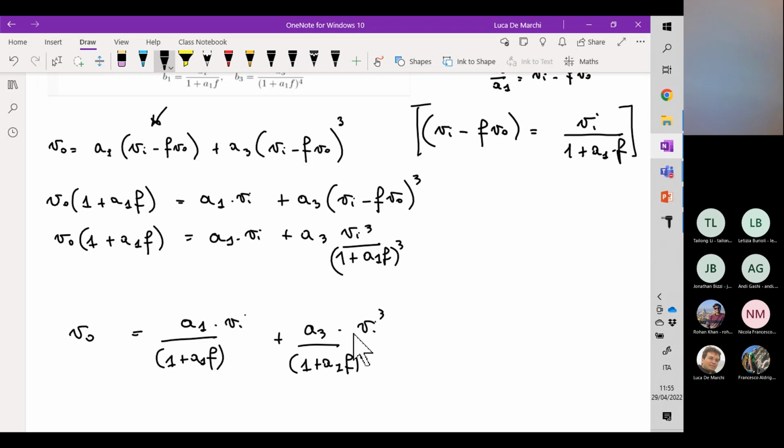Here you see an example in which the circuit is stable. This is due to the fact that the dashed line corresponding to A0 is quite high, at this level. So we look at omega null, which is again the angular frequency corresponding to a loop gain equal to 0 dB, which is the case in this specific point.